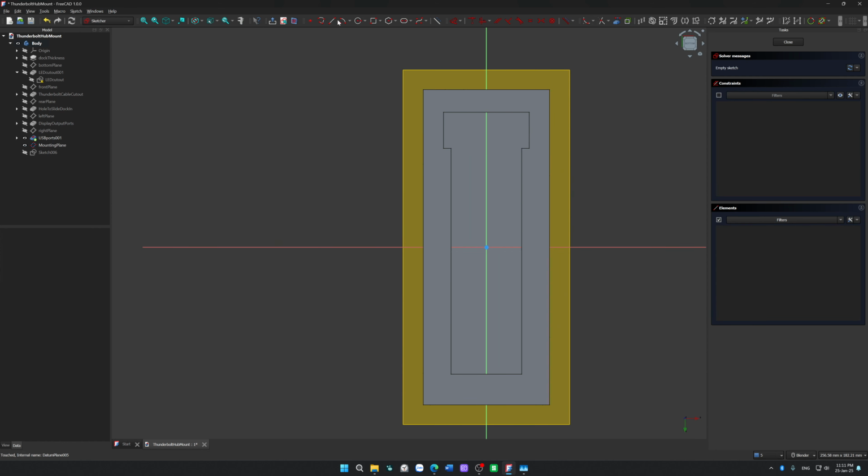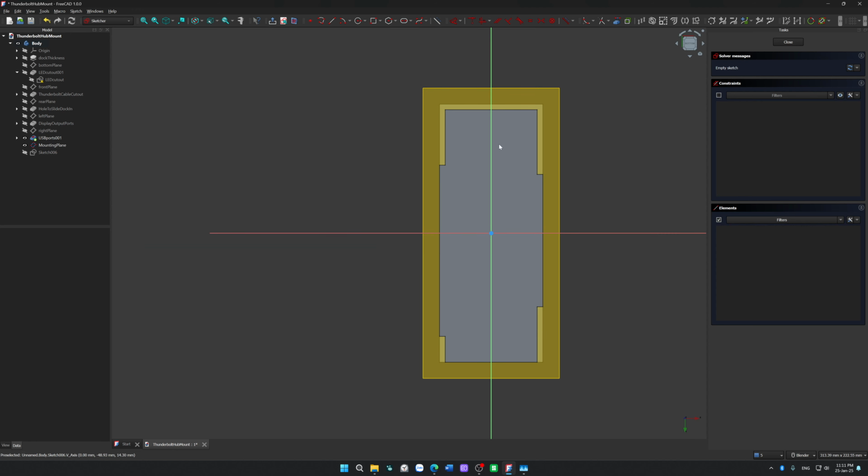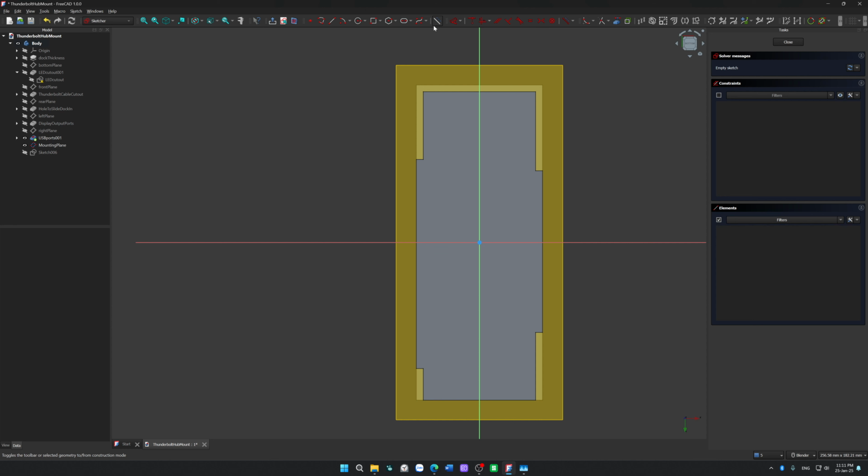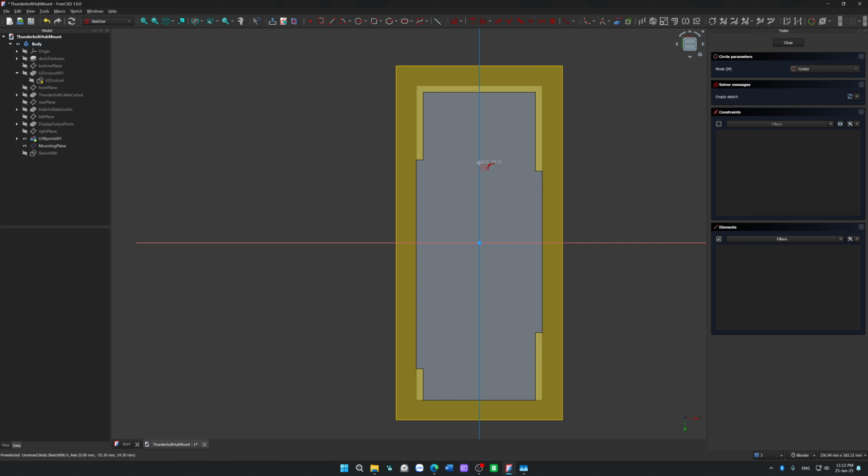A sketch on it. X-ray mode. I don't think we need X-ray. I don't think we need any reference from here. We can just take the hole, 3 millimeter. We will need 3 of them to create a line, right? So another right here, and another right here. Alright.